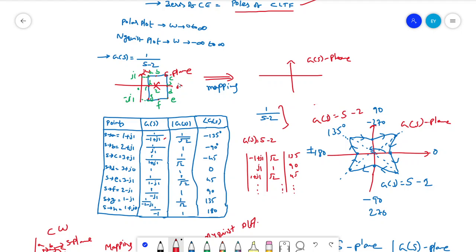And coming to the Bode plot, the frequency plot, what we are trying to do is get the phase crossover frequency and gain crossover frequency. From that we estimate the gain margin and phase margin, and through that we estimate the stability. So all those things are dependent on poles, right?